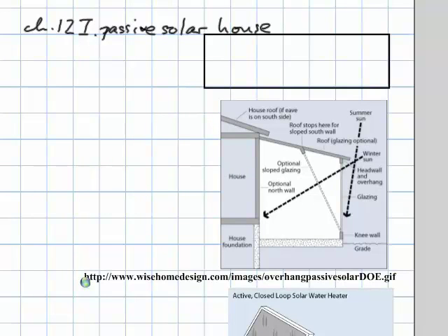So we're heating water here. Let's see what's given in the problem. They tell us what the heat flow is. So Q is given. They tell us what the temperature difference is. It's 17 Celsius degrees, and what it means is that the water does heat up to 38 degrees Celsius, but then gives off its heat to the rest of the house, maintaining it at 21 degrees Celsius, including the water itself. So that's why the temperature of the water itself goes down to 21 degrees Celsius.